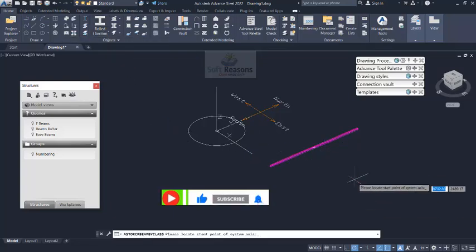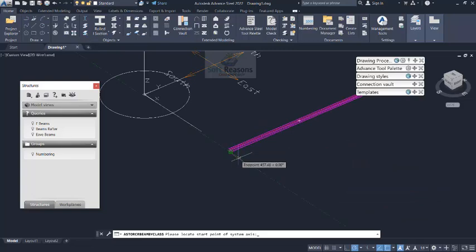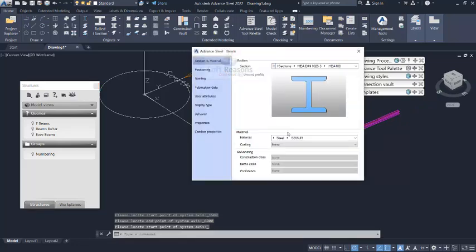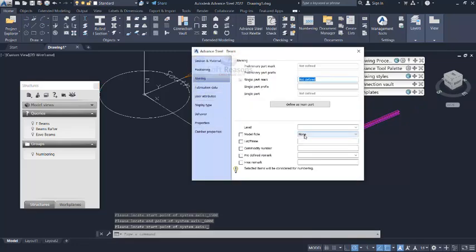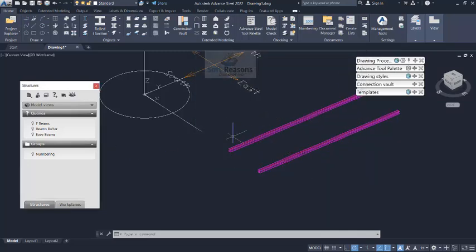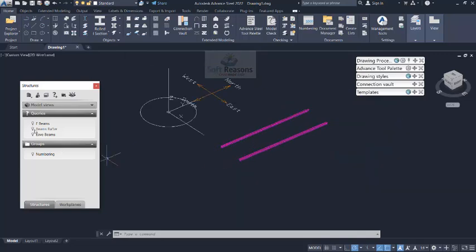I want to draw another beam right here. I will snap this point up to this point, let's say 1500, and enter. Get this way, and then I'll have 6000 millimeters and enter right there. Enter again. If I come to the naming, you see here is none, because the model row was not actually set as default. So I will click here and key in beam again. This is going to also be beam. I click on close. That has been assigned successfully.